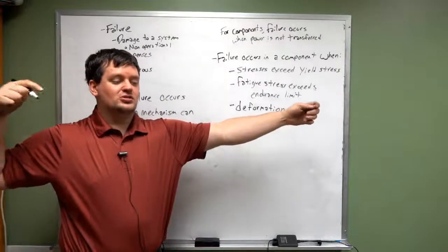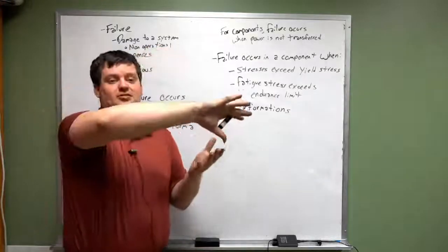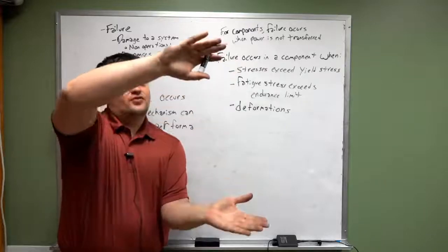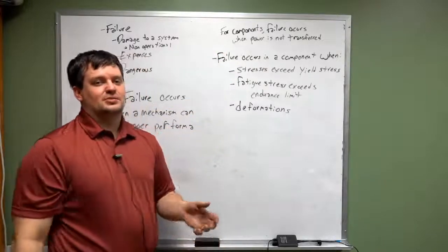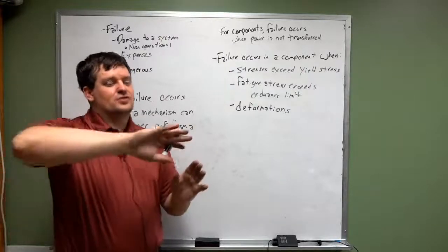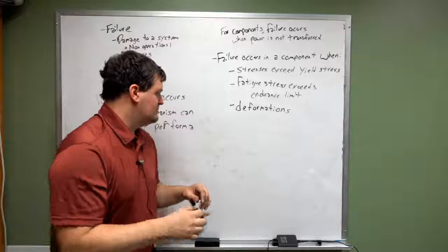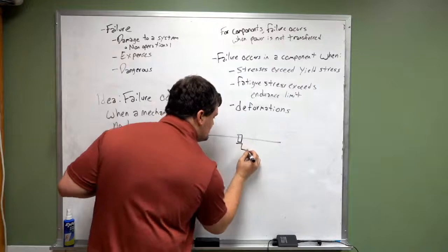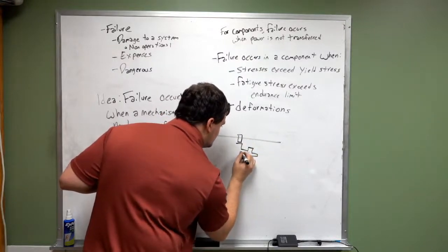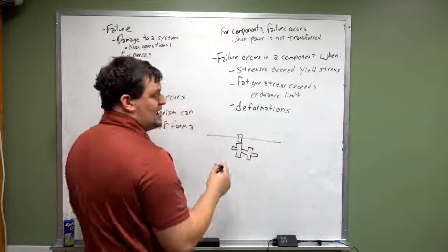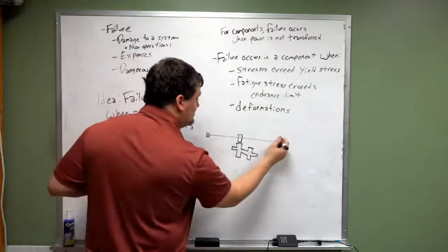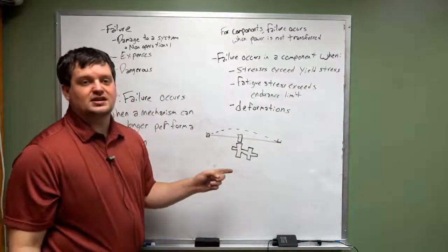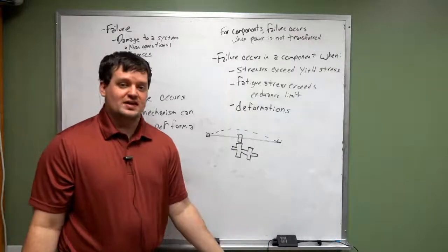If you have a really long shaft and you have a gear right in the middle, the problem is you're going to have a hard time transferring power because the amount of force that is needed to transfer power between those two gears is enough force that it actually causes the shaft to deform up the middle. So if I have a really long shaft and right in the middle I have a gear and it transfers to some other gear chain down here, okay, I may have failure if my bearings are at the end just because the deformation of the shaft is enough that these two gears are no longer in contact when it's trying to transfer power. I don't know if you've ever had that happen. It's really annoying.